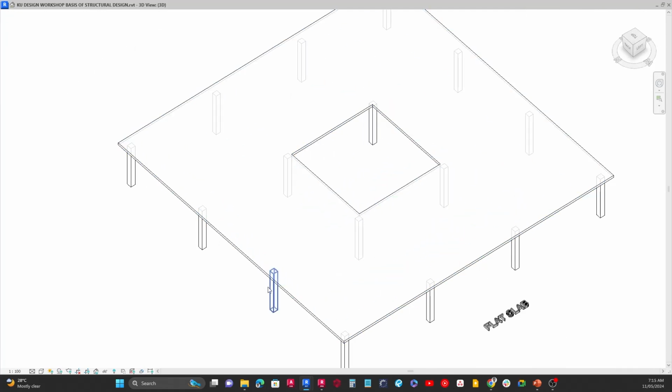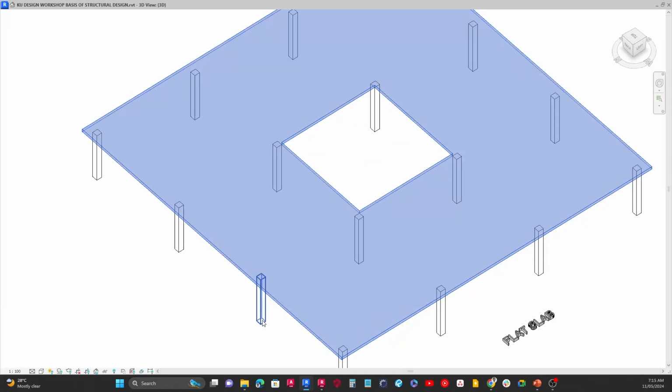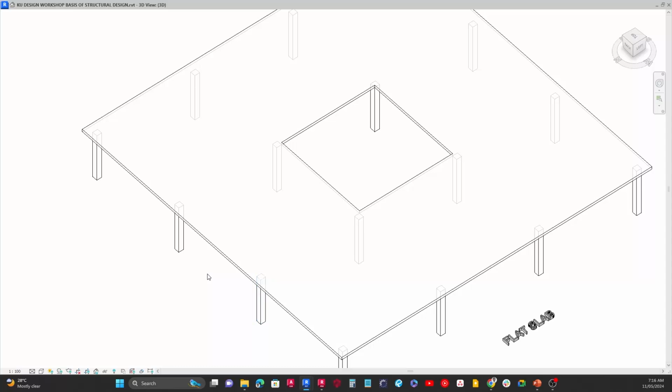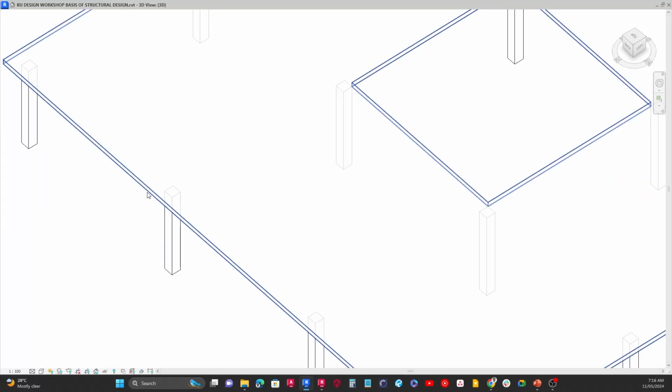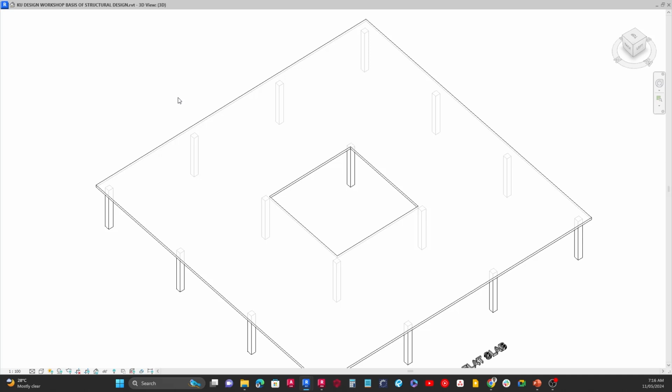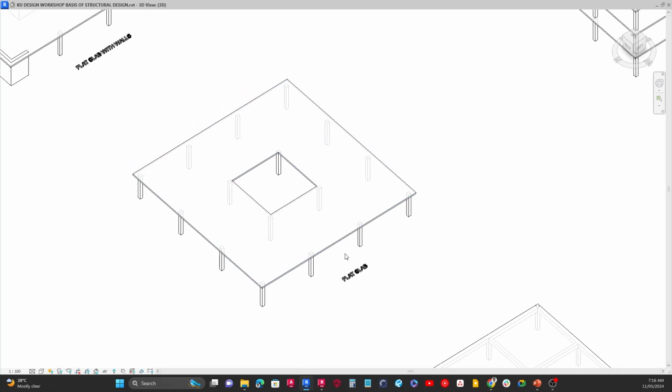Also, another disadvantage of flat slab is that if the slab is not going to be thick, the column sections will need to be bigger to reduce what we call punching. That's the interaction between the slab and the column. It's going to need larger column sections, or what we call a drop panel, meaning a small cap on top of the column to reduce the punching. But for aesthetic reasons, flat slab is always a favorite.